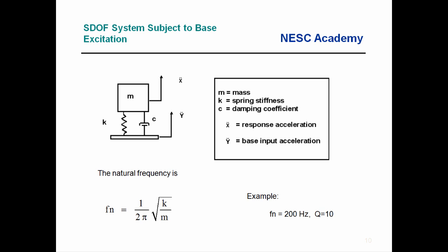That's the numerical engine we're going to use for our modal transient analysis. For those of you that have previously done shock response spectrum analysis, you most likely have used the Smallwood algorithm, whether you realized it or not. It was originally derived for that purpose, for short transient signals, but it works just as well for longer duration stationary signals or steady state inputs as well.